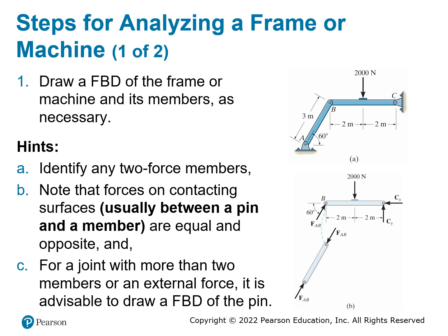If you use the method of the joint, this one is actually quite simple. Once you find the supporting force here, and you know this force is going along this direction, you can simply just work on the top member here to find a solution.